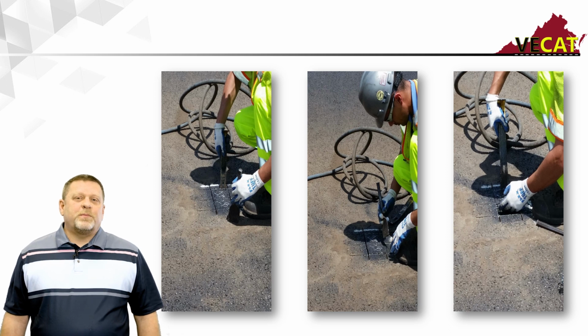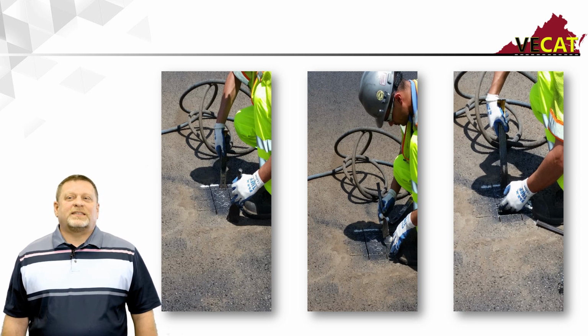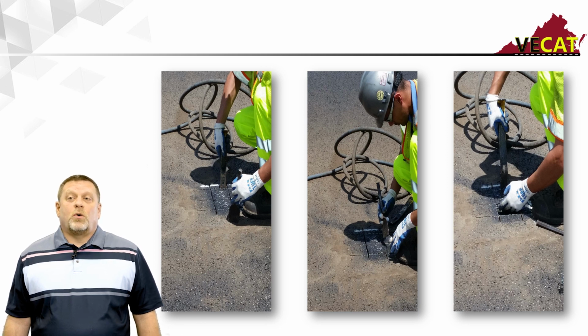I caution people using a screwdriver in this case, that the screwdriver is really narrow and it puts a focal point of pressure which can damage your specimen. And this is where you're going to measure your density, your actual density, so you don't want to damage it. It's important to have a wide spatula for this process, as you can see there in the first picture that he's using to help pry the specimen out.